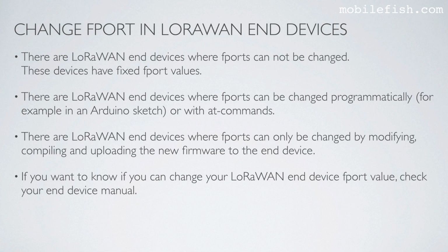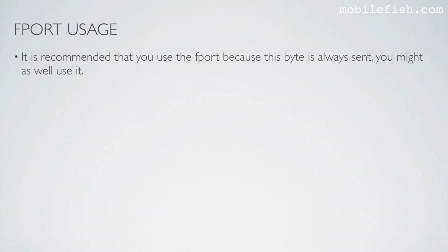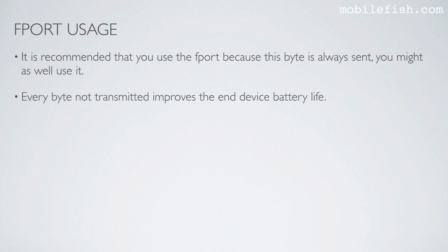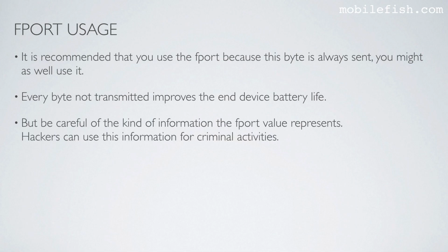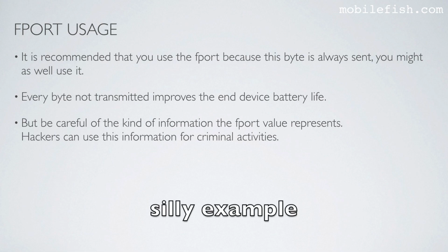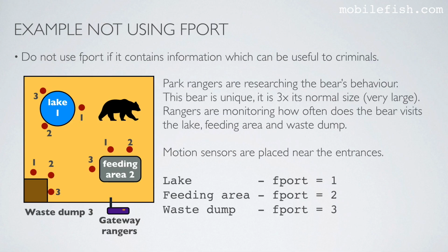your end device manual. It is recommended that you use the FPort because this byte is always sent. You might as well use it. Every byte not transmitted improves the end device battery life. But be careful of the kind of information the FPort value represents. Hackers can use this information for criminal activities. I will give you a silly example, but it will get my point across. So do not use FPort if it contains information which can be useful to criminals.